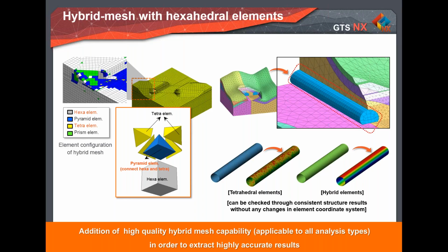So aligning the element coordinate system, especially for a plate when you model a wall or lining, becomes easier, and the contour we get with hybrid elements becomes more effective, especially while dealing with tunnels. The hybrid mesh provides an advantage over tetra mesh.